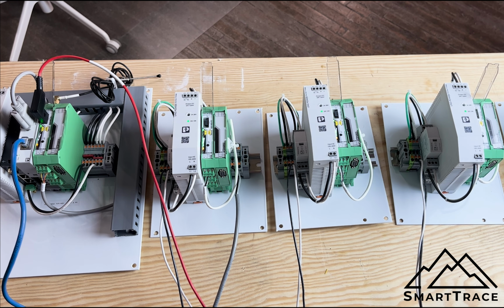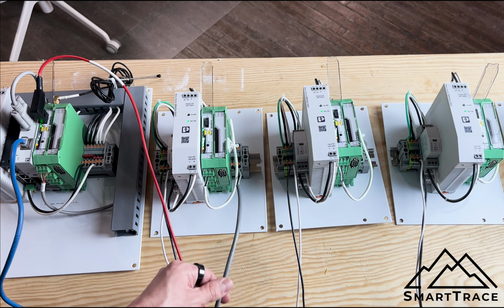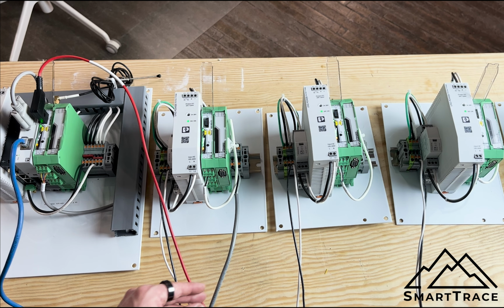This gets a little bit more advanced, but really quickly, we could always ping this device and see if we can see this device. If we can see this device, that's great. And then we could use a tool like Modbus Poll to actually individually poll or test each individual heat trace circuit and see where we're running into issues. Is a heat trace controller failed and locking up the loop? Is there termination issues, loose terminations, things of that nature could be it.